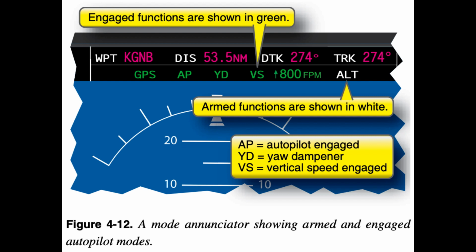Instead of monitoring altitude, pilots sometimes simply listen for the alert. This phenomenon is one instance of what human factors experts call primary-secondary task inversion, when an alert or alarm designed as a secondary backup becomes the primary source of information. In the case of the altitude alerting system, when the alerting system is missed, or you are distracted, nothing is left to prevent an altitude deviation.